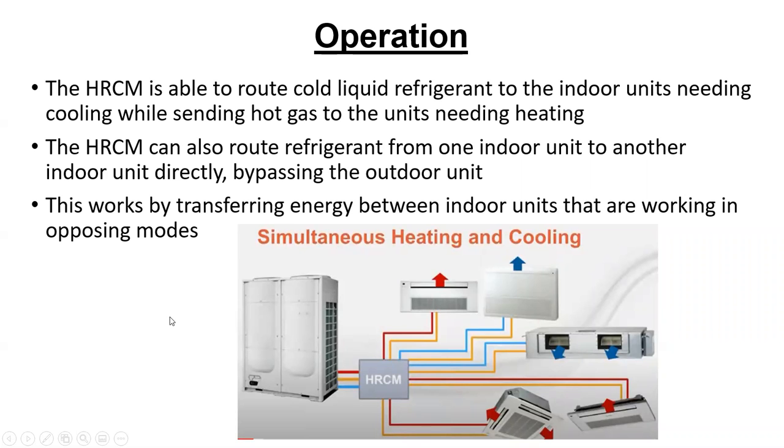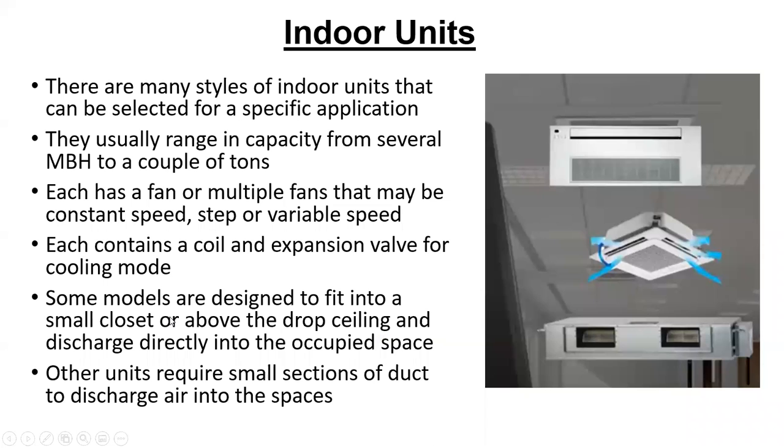It's kind of like that water source heat pump loop where we had a water loop circulating. It's really the same concept. It's just we're dumping it into the refrigerant instead of dumping it into a water loop. But then you've got all the chemistry, the pressure, the thermodynamic changes in the refrigerant that have to be accounted for here to make this work properly. So this works by transferring energy between indoor units that are working in opposing modes. Okay, indoor units, and we'll have more on this module here in a minute.